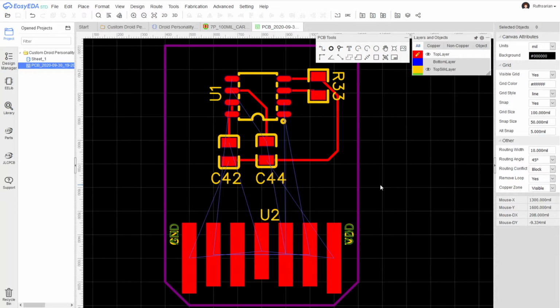This is where there's a million different ways to do it, and it's not necessarily that all of them are equally good or bad. Because of the size of the board, you could wire this up probably any way you want. You could run traces all over the front and the back, and it'll be fine. On larger boards, on more complex circuits, how you lay out the traces on your board can have serious impacts on how the board operates, or it might not work at all.